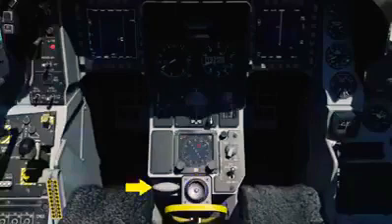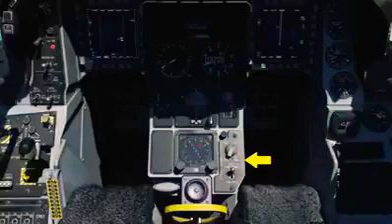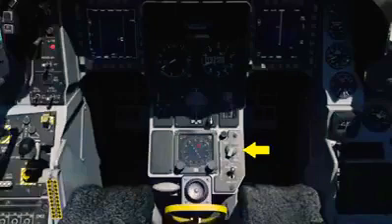In the real aircraft, the pedal adjustment handle allows the pilot to adjust the distance to the rudder pedals. The Fuel Quantity Select panel allows you to determine what fuel information is displayed on the fuel gauge. Test will place both pointers at 2,000 pounds and the totalizer at 6,000 pounds. In norm, the AL pointer indicates remaining fuel in the aft left reservoir in the A1 fuselage tank, and the FR pointer indicates the sum of fuel in the forward right reservoir tank in the F1 and F2 fuselage tanks. Reservoir moves the AF and FR pointers to display fuel in the aft and forward reservoir tanks.